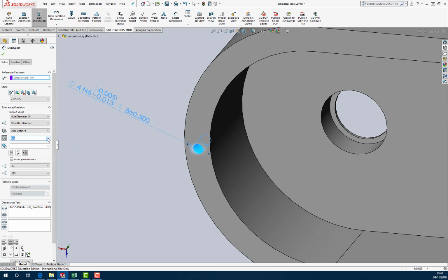If you want a bit more interference, go up to something like a P6. You're then starting to get a little bit too much interference, so an N6 will probably do the job for this. N6 or even an N7, what the heck. Let's go with an N6.